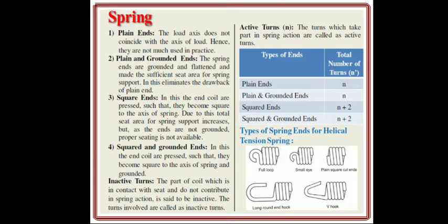What is a plain end? When to use the plain end? The load axis does not coincide with the axis of the spring, so in that case they are not much used in practice. That's why it is not majorly used in applications. Now the second one, the plain and grounded end. The spring ends are ground and flattened to make sufficient seat area for the spring support. So this eliminates the drawbacks of the plain end.